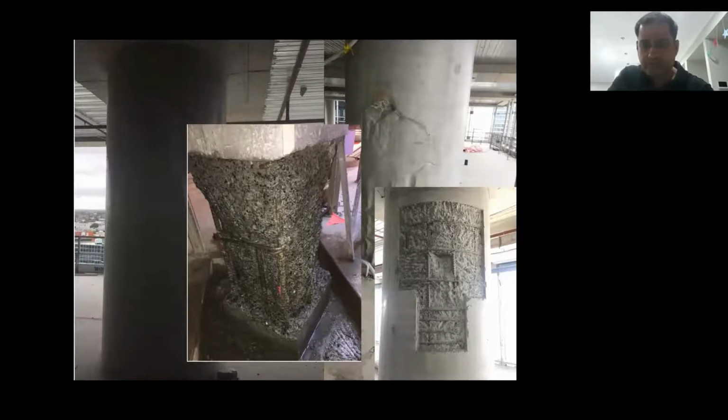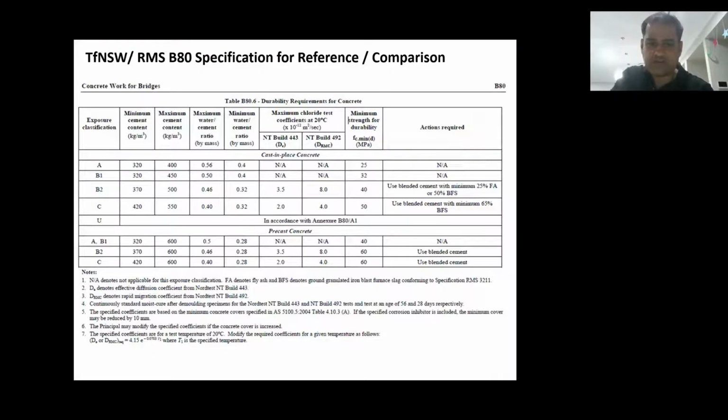These days there are repair mortars which are available as self-compacting concrete, similar to those that have been used in Burj Khalifa, but they are available in pre-bag. That means you don't have to bring your transit mixer with 9 cubic meters or whatever for such repairs. You can use pre-bag micro concrete pourable materials to repair such voids in structural elements by creating what we call form and pour. So you create a letterbox formwork and you pour your material and it would just reinstate it 100%.